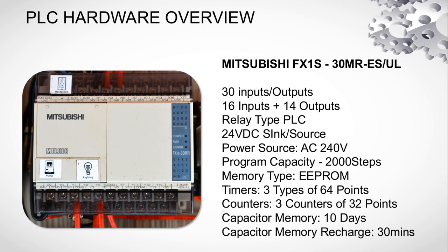Its power source is AC 240 volts, which is applied at this part. You have the live and the neutral, and that is where you apply the power. So you have to exercise a lot of caution when you're working with this type of PLC.